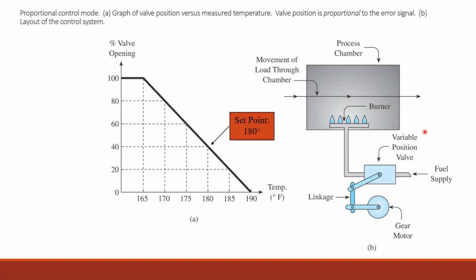The proportional control is a type of controller that provides a little tighter control over those oscillations. Because it's not slamming on and off, it's proportional. The output correction that's being performed is proportional to the amount of error that exists between the process variable and the actual set point.